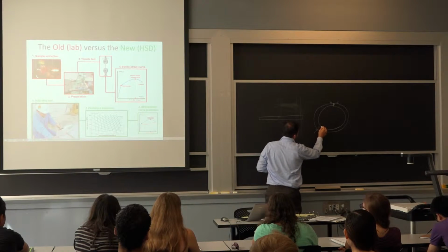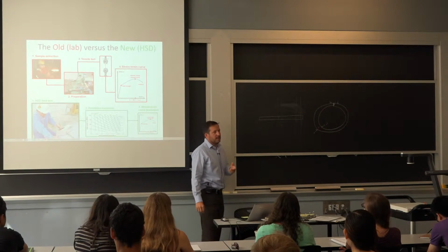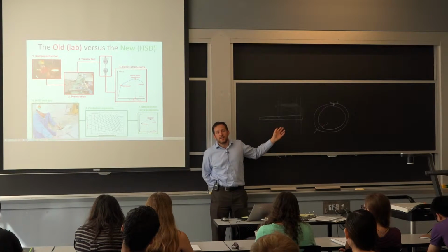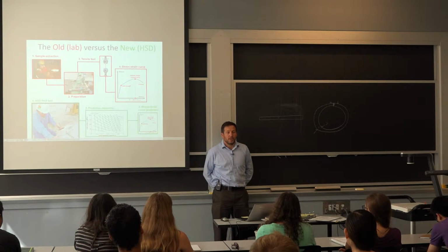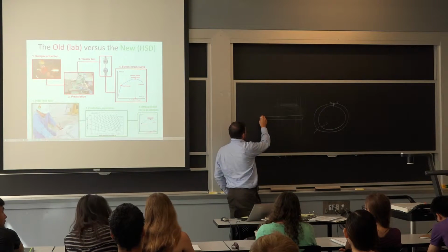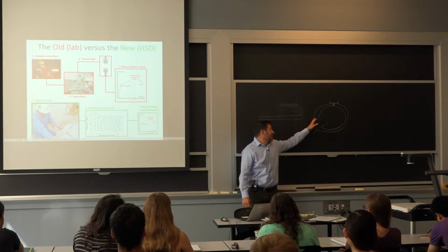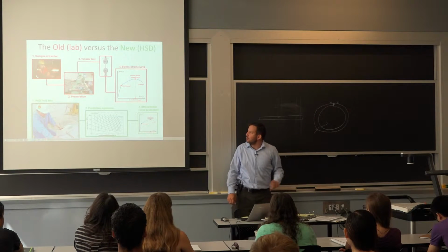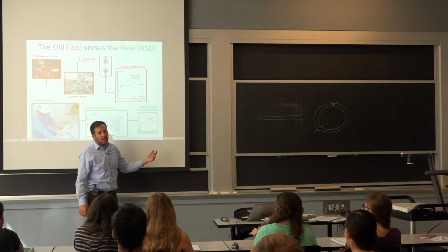And how do I know what the value is on the inside? The metal processing, the processing of steel for this type of application that we're going to go through in more detail, really helps to figure this out. It turns out in general you do have a homogeneous microstructure when you start. When you bend it, yes, you work harden the surface. So you're starting to move on that stress-strain curve, so the surface becomes harder than the center.